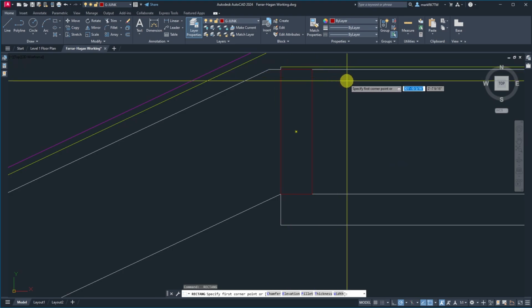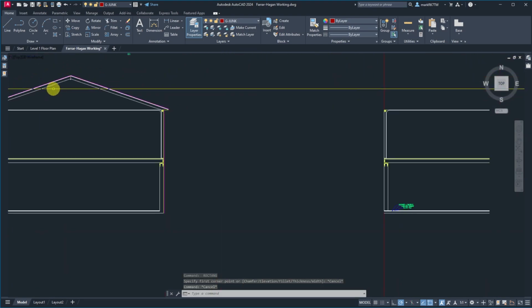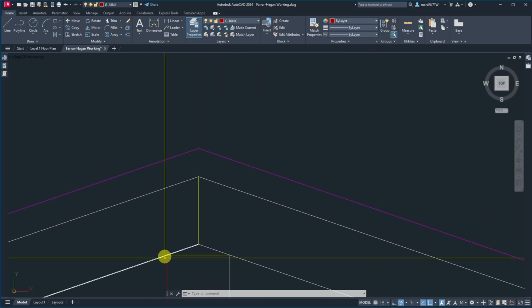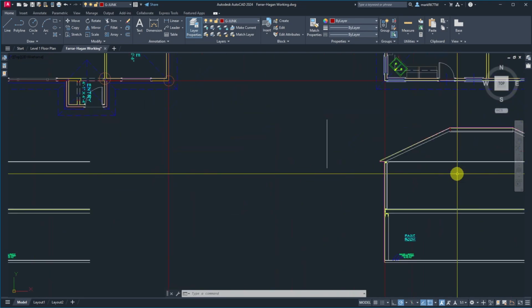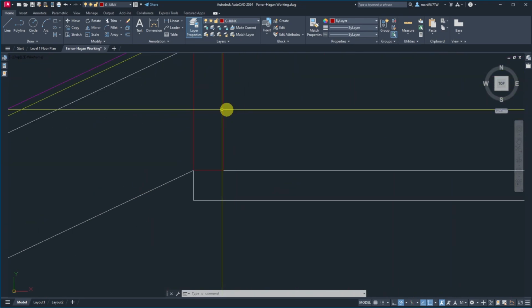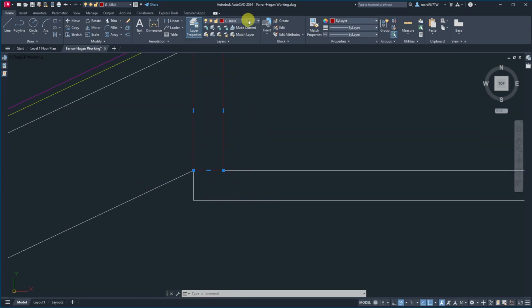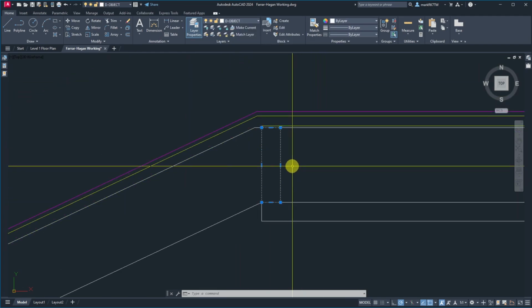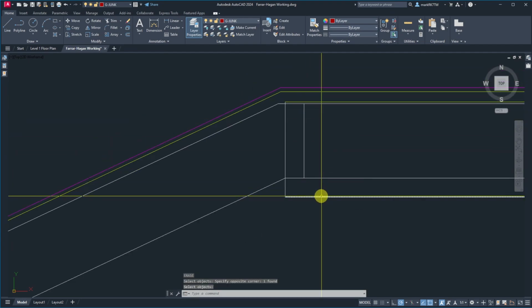Now this line up there is what? This higher portion. Our lower line is where our stuff stops. So we're in good shape. So our rectangle's there, it's good. Let's grab it. There's our polyline, and we're going to take it to D-object. And then we can get rid of that line that was here.